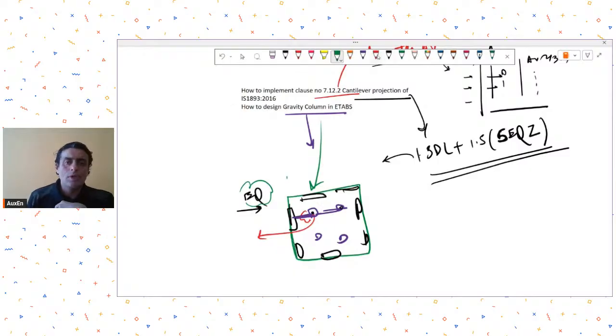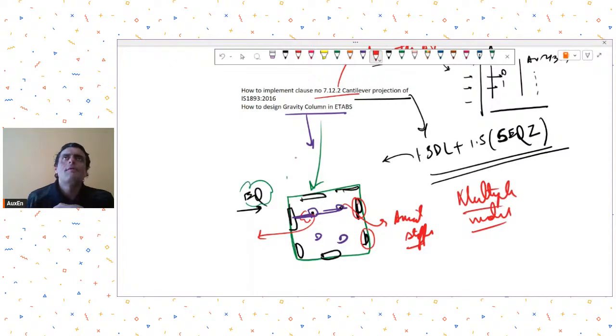If you provide very little axial stiffness to your columns, the problem is that the axial distribution to walls also changes. So then you will have to make multiple models, and maybe you assign something like a pin support at the column points and run your analysis, but then it changes the stiffness also.